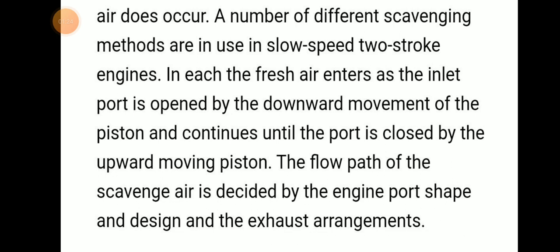In each, the fresh air enters as the air inlet port is opened by the downward movement of the piston and continues until the port is closed by the upward movement of the piston. The flow path of the scavenge air is decided by the engine port shape and design and the exhaust arrangement.